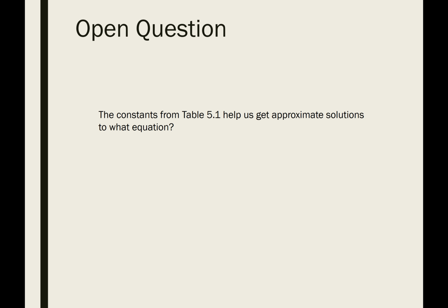Yeah, Nimdo? So we have different solutions because we have different boundary conditions. And so do the boundary conditions change because we assumed the lumped capacitance? Is that why the initial conditions change? So for these particular solutions, we're assuming that our initial condition is just constant temperature everywhere.